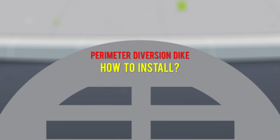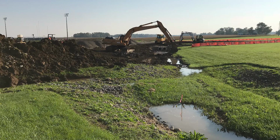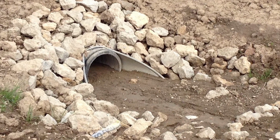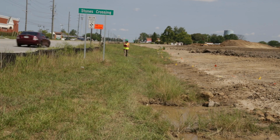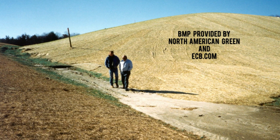How to install. Construct the diversion to dimensions and grades shown in the construction plans. How to maintain. Remove sediment from channel to maintain positive grade. Check outlets and make necessary repairs immediately. Repair dike to its original height. How to inspect. Inspectors should check for evidence of sediment in the channel, as well as the outlets for evidence of sediment and to determine if they are stabilized.